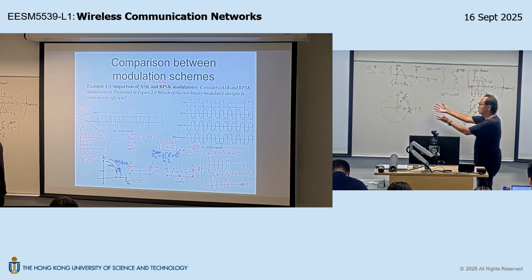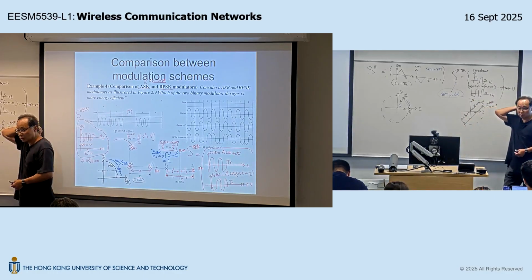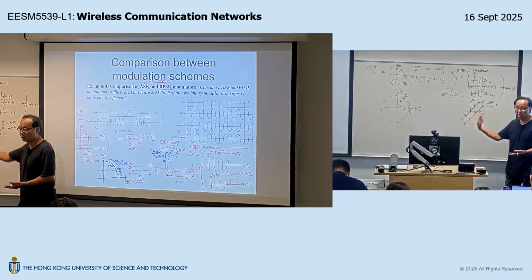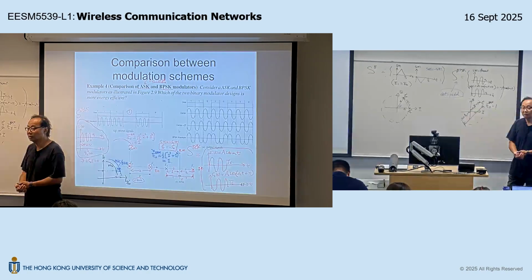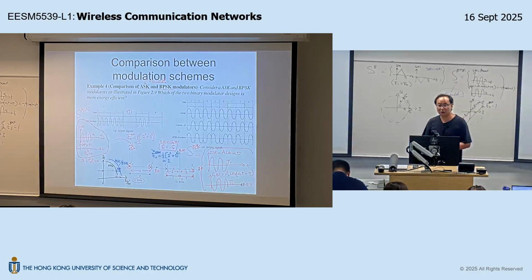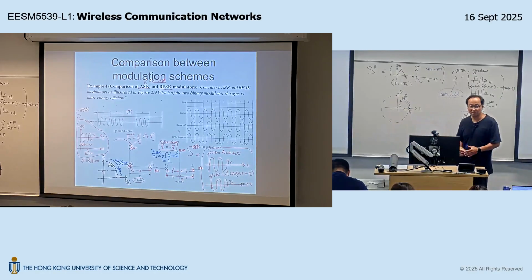We can just look at this geometric domain constellation points configuration and directly compute or do the comparison. Is that okay? So that's why in most textbooks or data sheets, you don't come across the specification using time domain very often. Most of the specification of the signal set behind a modulator is specified using a constellation diagram directly. Is that okay?